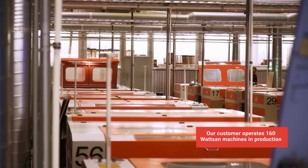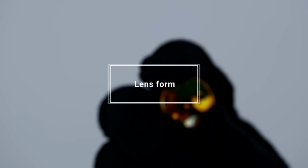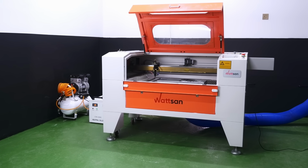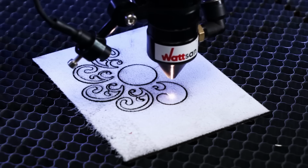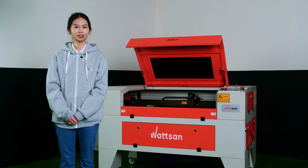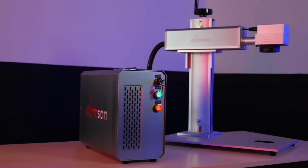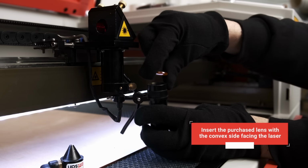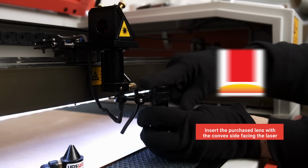Now, to the form. Lens form. Lenses come in different shapes, such as plano-convex and meniscus. However, when working with standard CO2 machines, we won't notice the difference. To perceive it, you would need to use an expander, like in laser markers. So in this case, only one thing matters. Insert the purchased lens with a convex side facing the laser.